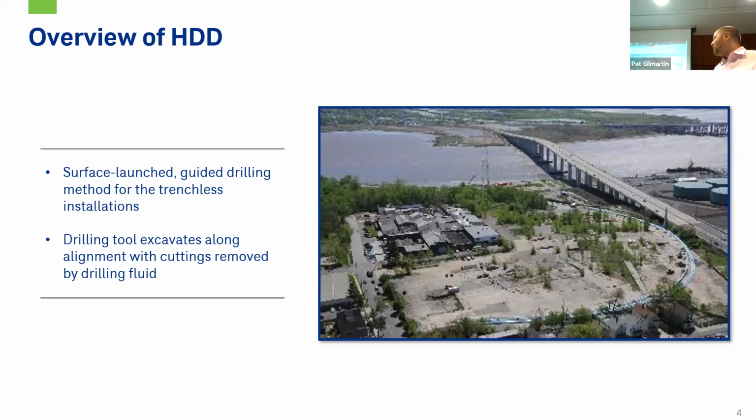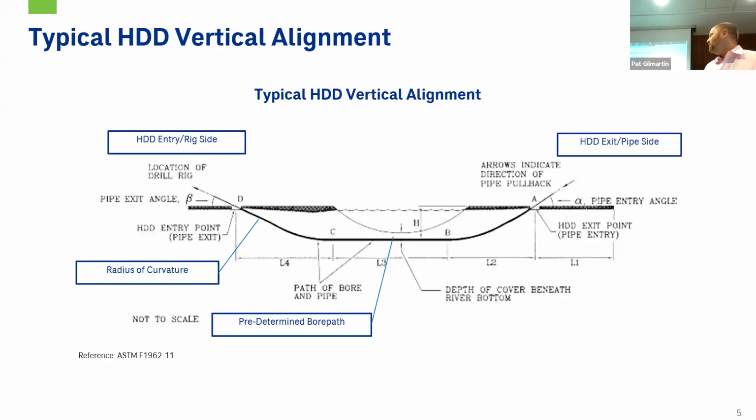You need an offset from wherever you're going. And so as opposed to a vertical shaft that you typically have for most trenchless construction projects, you're having to do that offset in order to get underneath whatever you're crossing, whether it may be a wetland or river or other objects.